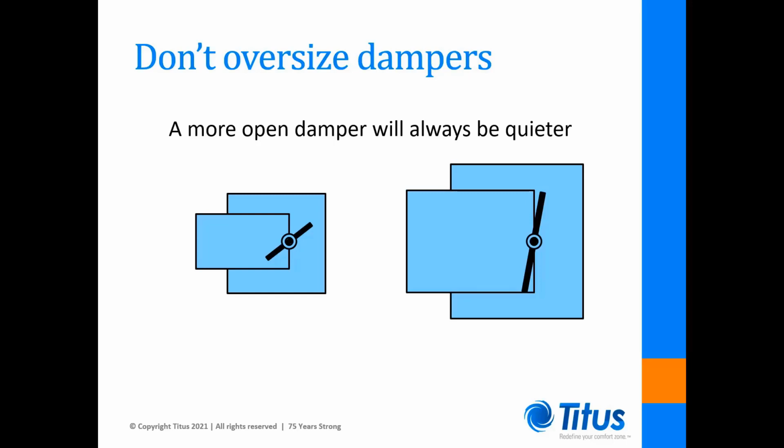This is due to the air jetting around the damper seals, causing them to vibrate. The amount of noise generated at various frequencies is dependent on the damper design, condition of the seals, roundness of the duct tube, and the exact pressure being applied. These are variables that no software can take into account, so the noise level can't be predicted at turn down. Don't fall into the trap of oversizing dampers.